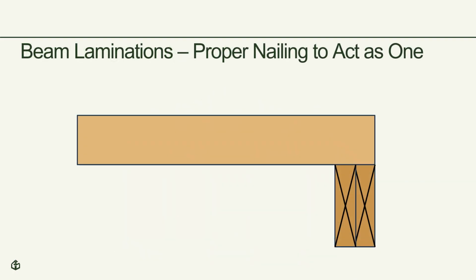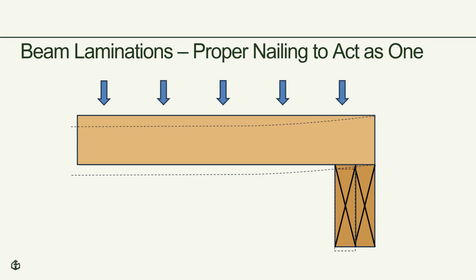When the header tables require multiple laminations, for example two 2x8s, it's important that the laminations are nailed together per Table R602.3(1). If it isn't, then the interior side lamination will take the force first, making it subject to failure. You can see this more clearly by these lines showing how the floor joist bearing on the header starts to deflect. Its weight will impact one of the laminations first. Proper nailing ensures the laminations act as one.